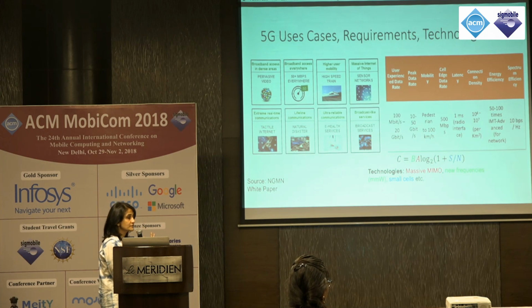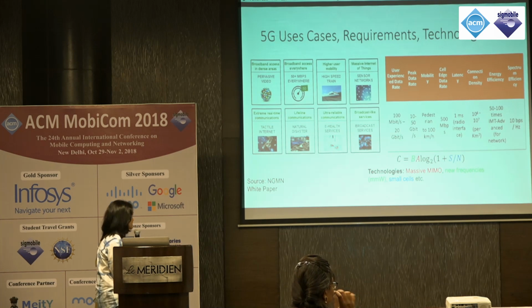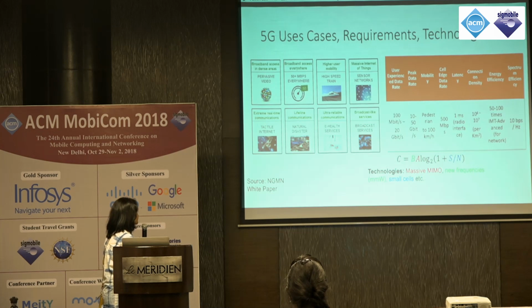And the signal to noise ratio, you keep it high by making sure your deployments are small cells. So you basically artificially limit how low your signal to noise ratio is going to be before you hand off to another small cell. So in terms of where we are on the physical layer with 5G, we are pretty much hitting all the 3 knobs that we have in the capacity equation.